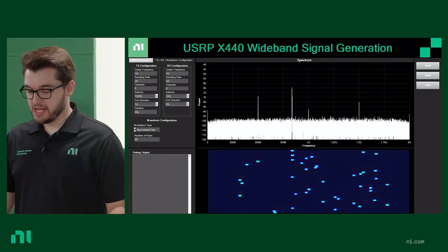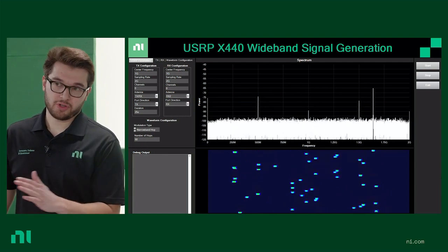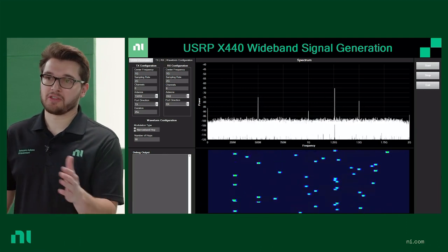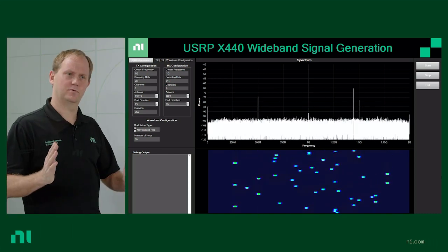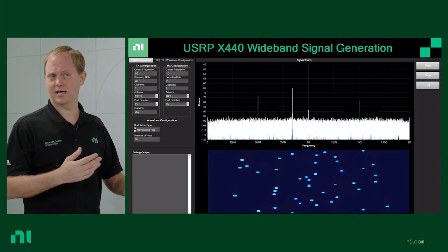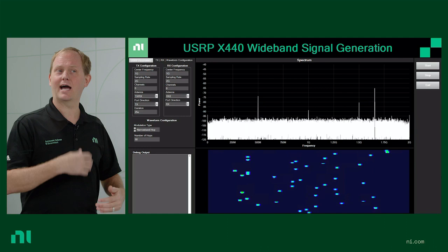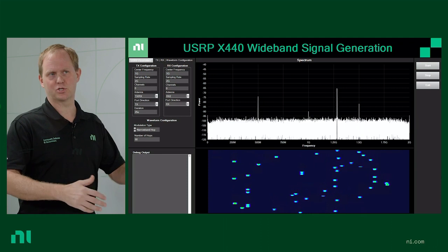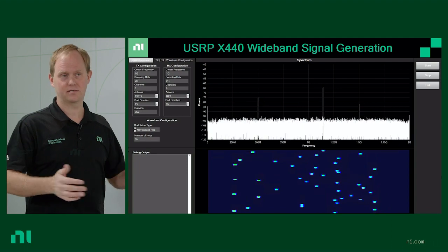What we're looking at here is a radar emulated signal where it is hopping across the spectrum, which you can see on the top graph there, across that 1.6 gigahertz approximately. And on the bottom, you can see the randomness of the frequency hops in that waterfall plot. So that's pretty cool. You're able to rapidly tune within that bandwidth, almost instantaneously, and that allows engineers to prototype novel waveforms for things like AI-driven or cognitive radar and electronic warfare type applications, where you're emulating certain threats to be able to either prototype or test certain assets with this type of capability.